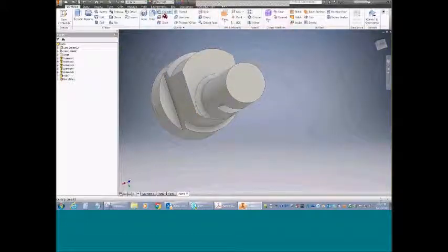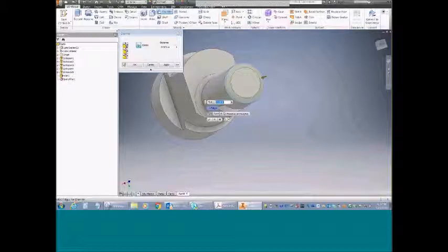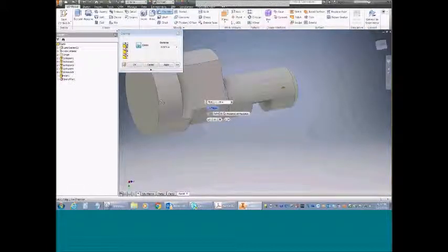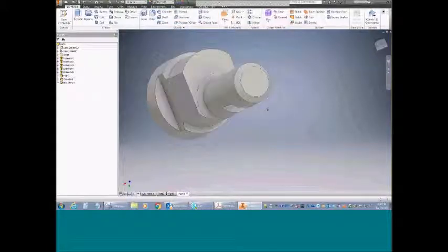And I have a couple of chamfers. Same thing, different possibilities for specifying your chamfers. I would cover all that with the students. They are 1/8 of an inch here, so I can just select my chamfered edges, spin this around. Here we go. So we're able to get that done in pretty short order.